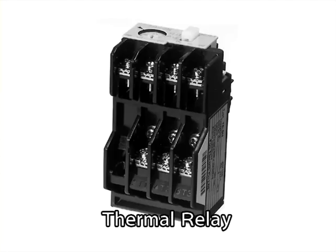The thermal relay is composed of a main circuit terminal with a built-in heater and bimetal, and an auxiliary relay. It is used to intercept the circuit when the latter exceeds a certain limit. In the sequence circuit, it is possible to detect overcurrent using this auxiliary relay. The auxiliary relay will not return to its original state even if the excessive current is stopped. Therefore, it must be manually reset once the excessive current error has been resolved and safety has been confirmed.